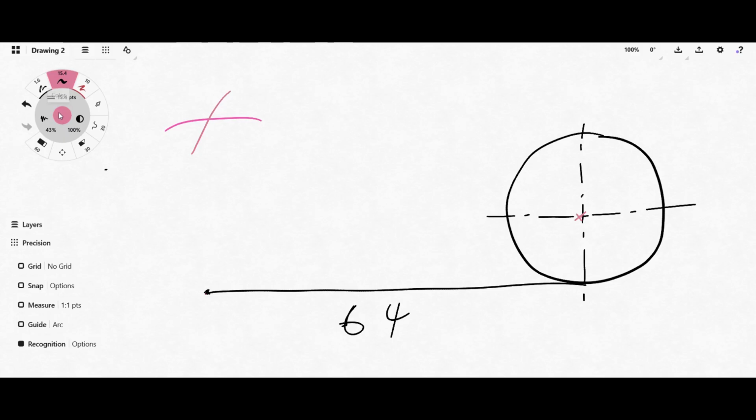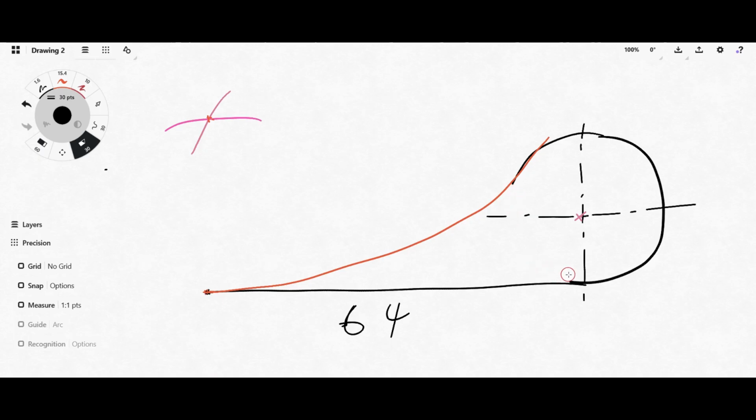That gives you a center point, and if you open your compass from here to here, if you do a good job, it should be equal to 51 and touch the circle, right? Or you can also measure 51 with your rule, and then draw your arc there. Then you clean this part.